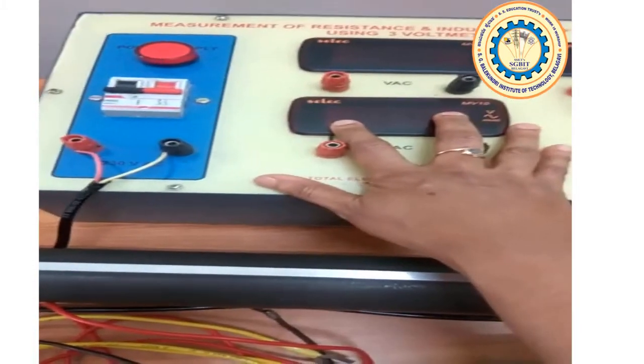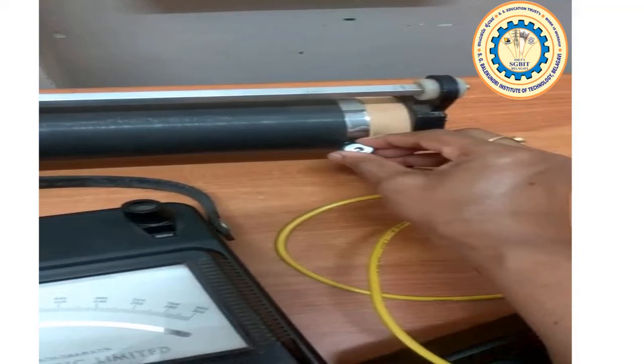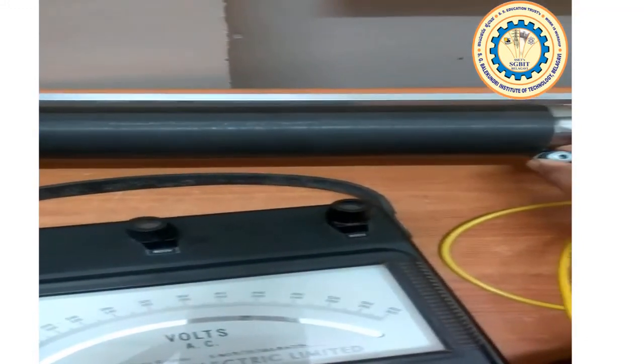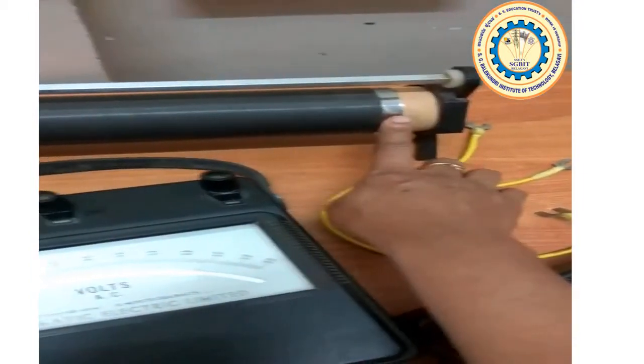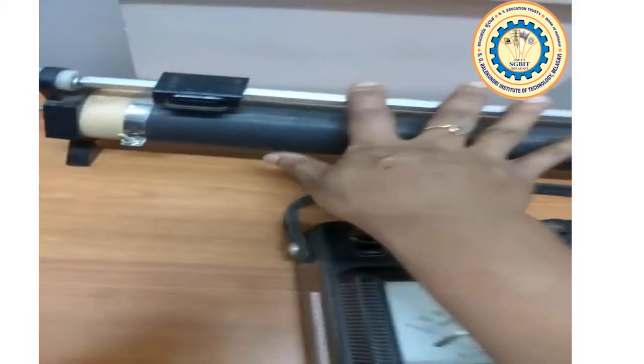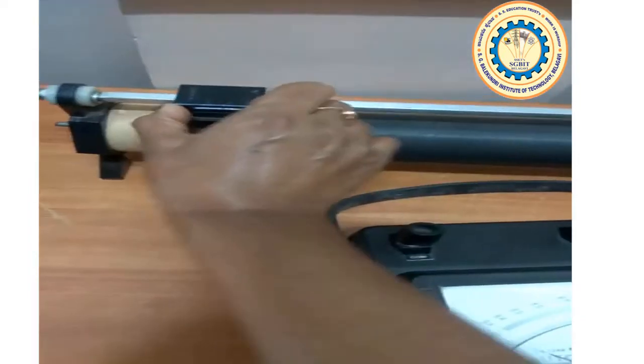but from the kit we are going to take only the supply. Then we have the rheostat. Here in the rheostat we have these 2 terminals as well as one more terminal. These 3 terminals are provided in the rheostat. If we want to use the rheostat with constant resistance, then we have to connect between this point and this point. If we connect between these 2 points, then this is considered as variable resistance, and we can adjust the resistance by moving this knob.